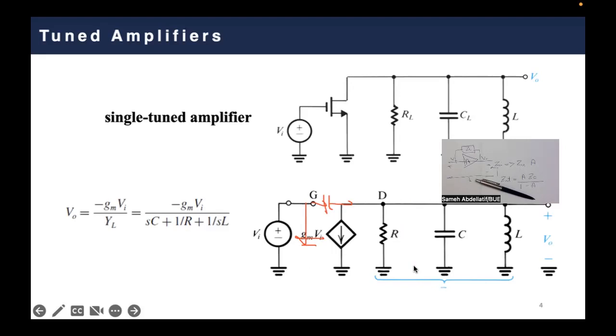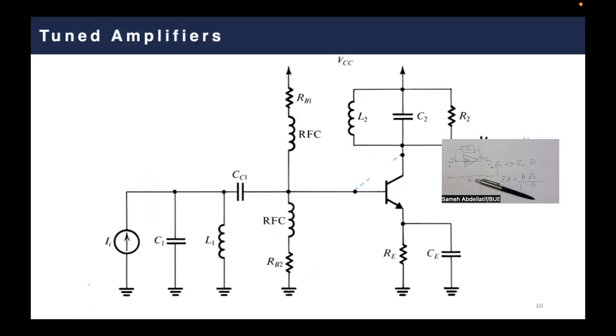Similarly applied when we go back to this structure in the BJT. Again, the same will happen: we are going to split this base-collector capacitance into two capacitances, one in the collector side and one in the base side. And again, the one in the collector side is much more important because this will impact the overall capacitance of your RLC filter.